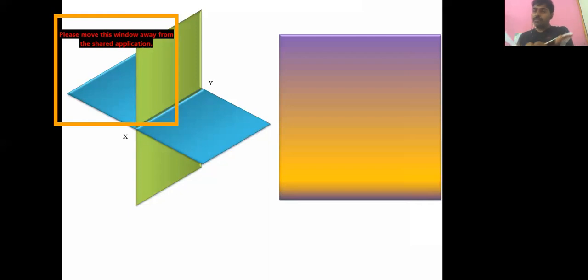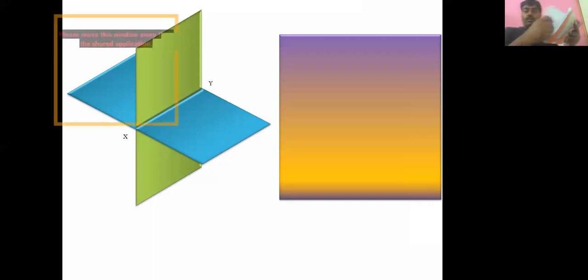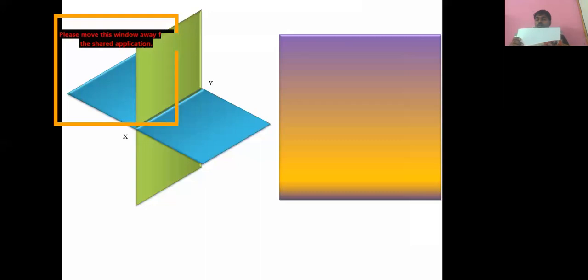Now the same thing for the second quadrant here, please. The second quadrant is like this. Now how am I going to define it? I'm going to define it like this: above HP, behind VP. Because I am on this side now. The sheet is like this for me, and it looks like this to you. I am on the back side. Can I see this point now? The point is not visible, so I said behind VP. It is behind me, behind VP.